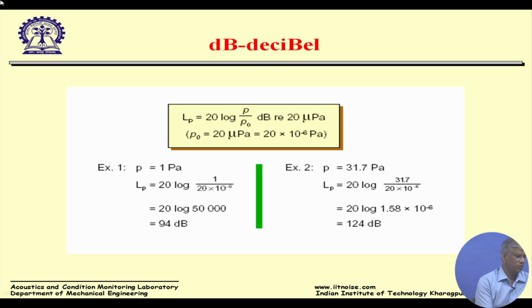So, just to recap, you all perhaps would be knowing by now, this logarithmic representation of the sound pressure level, because of the fact that the dynamic range is very high to represent in a linear scale. So, a decibel scale or a logarithmic scale is convenient to handle such large quantities. But I always caution my friends and students, never add decibels. Log m plus log n is not log m plus n. Okay, so please do not make that mistake.